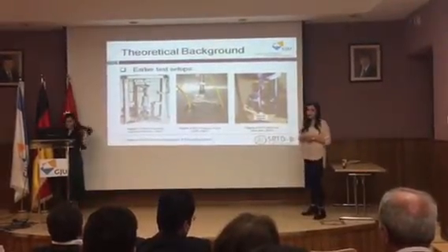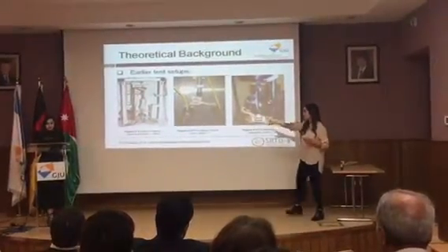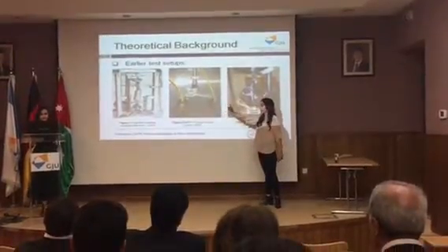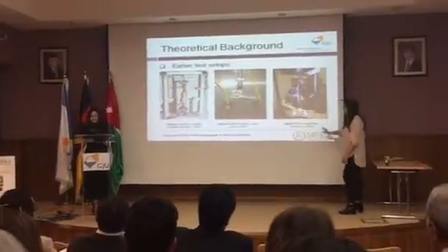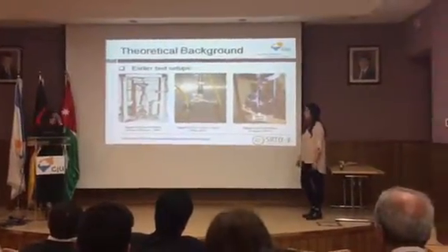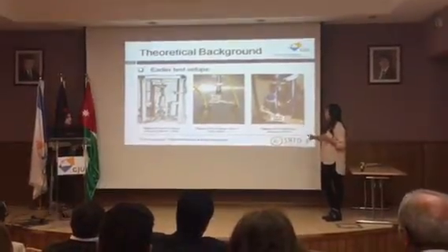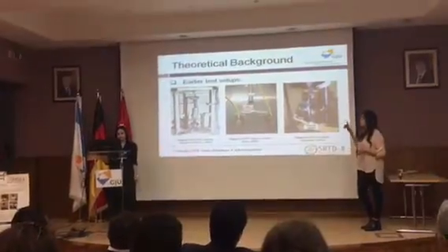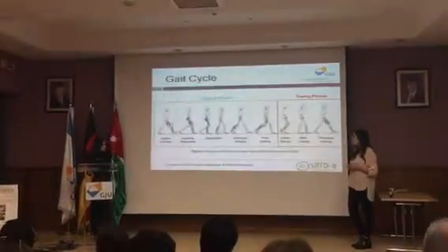The second one, shown in figure 2, is the NPO fatigue tester. It was developed by Ziolo in 2001. It uses, however, air compressors that drive pneumatic cylinders that inflict loadings on the prosthetic. And the third one is the MTS machine, which has been used by Berglund in 2010 in order to test the prosthetics. It utilizes a 4-bar mechanism in order to mimic gait.